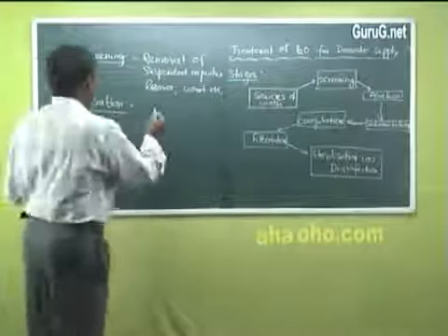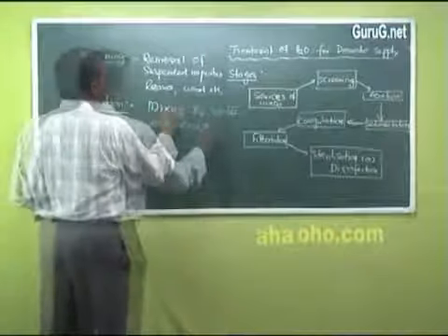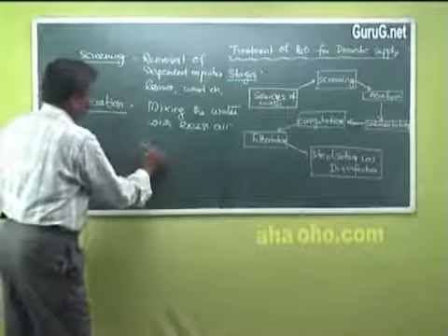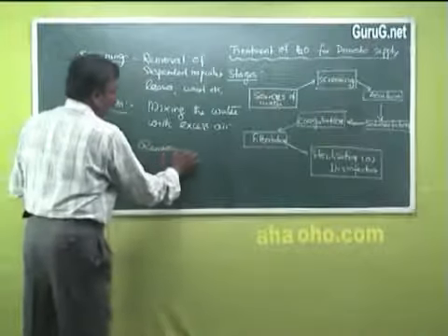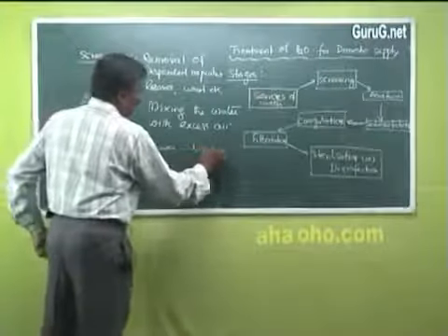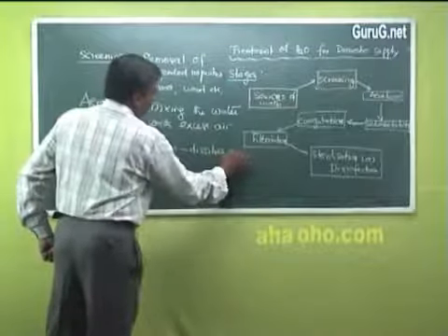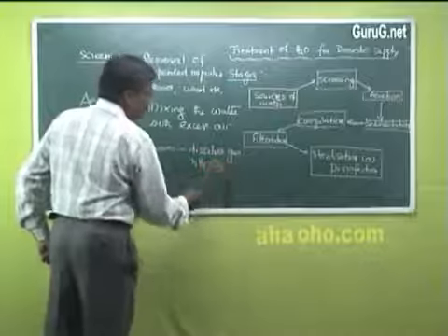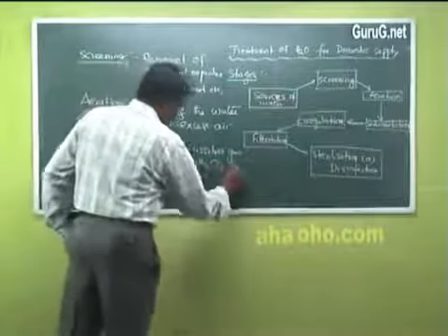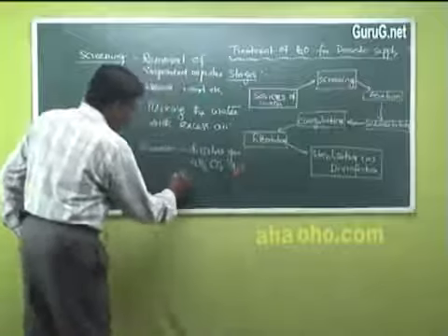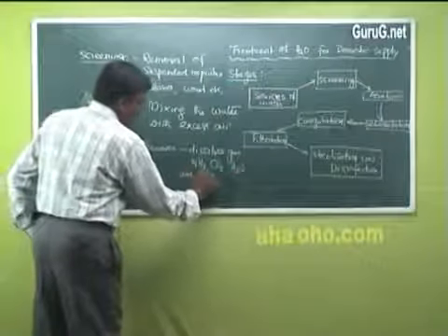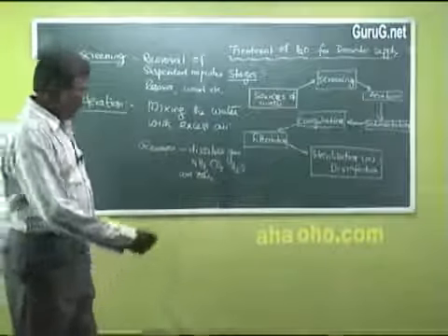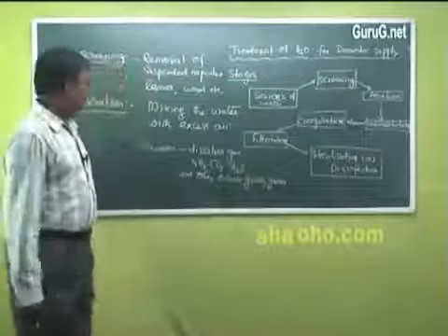That is one thing. Nothing but mixing with excess of air, it removes dissolved gases like ammonia, carbon dioxide, hydrogen sulfide, and other odor giving compounds. Gases are removed.